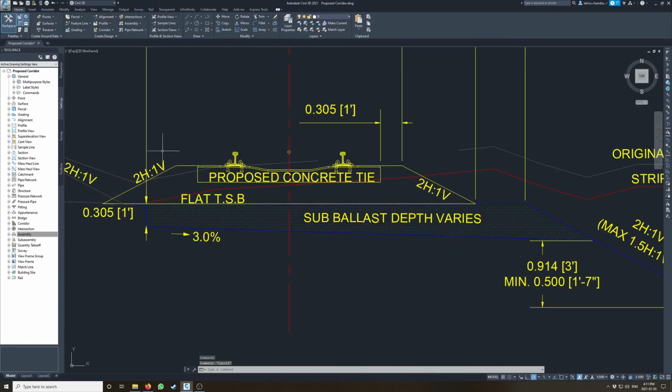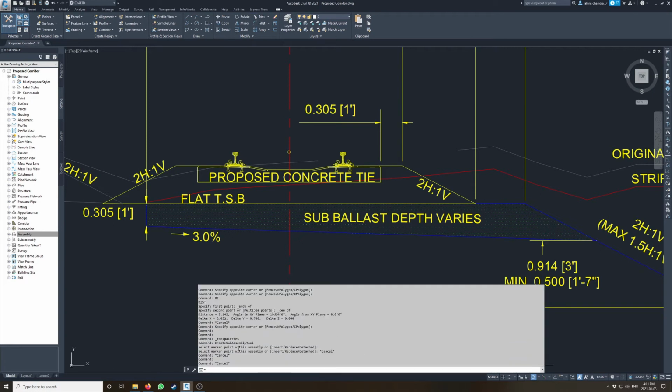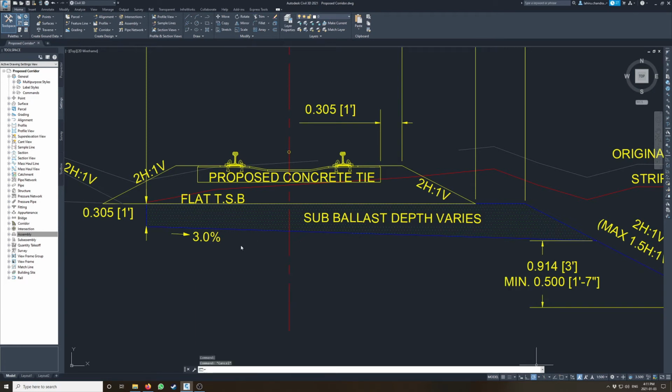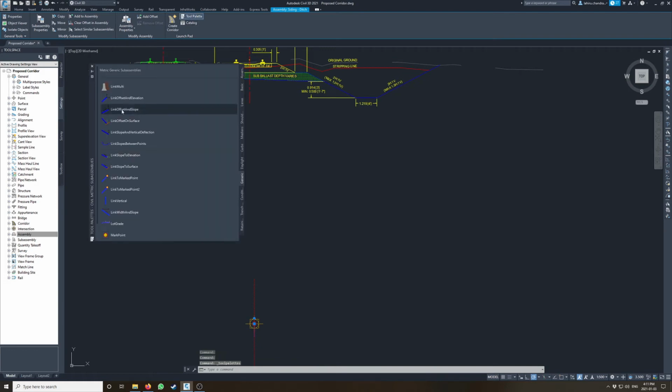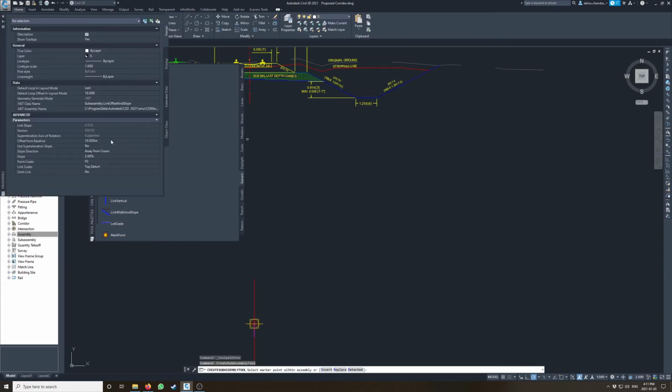Next thing, we want to move it to the left, 2.022. So we'll go back and we can use offset, link offset and slope. So to the left will be negative again, so 2.022. Slope we want to be 0 because we've already moved down by the required amount. These two once again will remain as is because we will eventually omit this code.